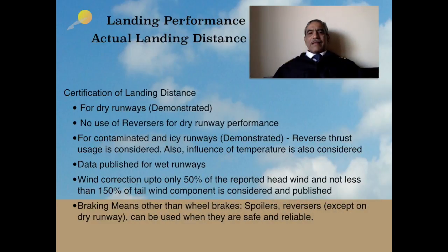Let me explain some more regarding this demonstration for certification purposes. Now, for a dry runway, the actual landing distances are demonstrated. May not necessarily be for wet runways and other contaminated runways. No use of reversers is being considered for dry runway performance.